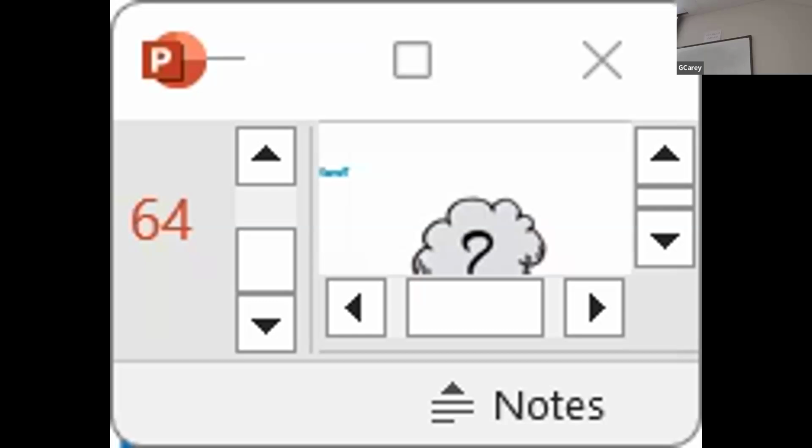As you back up and develop this 110 feet, think of the squared relationship. Change the flow, change the pressure drop. It's a squared relationship. So as the flow reduces, the system pressure drop is almost a quarter of what it was at design flow. Half the flow, a quarter of the pressure drop.